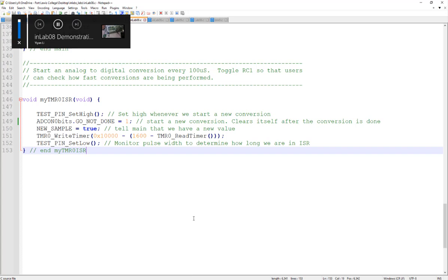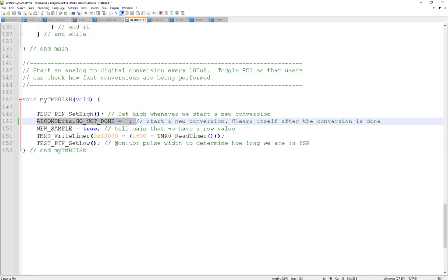So it's sampling. It comes here, and this one samples it. That's it. It gets into this interrupt every, let's say, 100 microseconds. Sample it, and then go back to wherever it was, right? And then 100 microseconds later, come back to the ISR, sample it. That's it. You don't even need to do anything else. Everything will be mastered by this function. All right, we'll talk more about it on Monday. Thank you, Professor Lee.